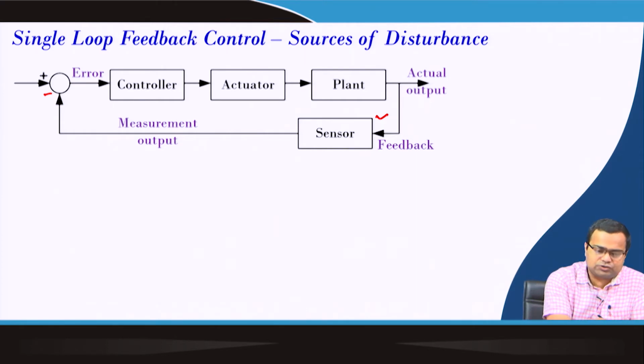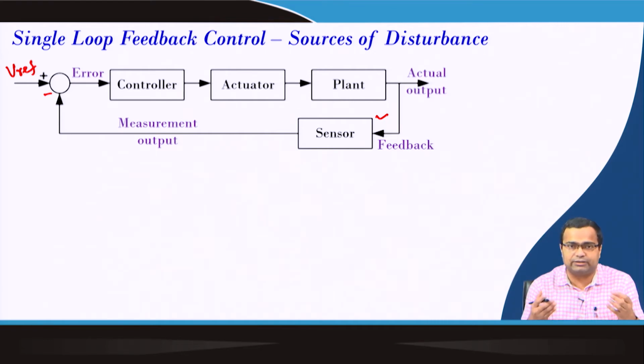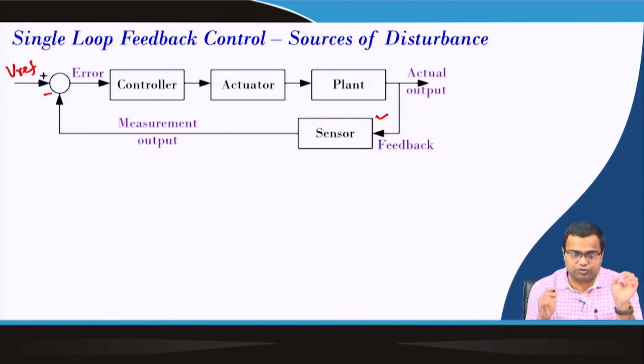Then this goes to a comparison with a reference signal. This reference can be a voltage if it is a voltage regulator. If it is a current regulator, this can be a current reference, and we need to sense the current which we want to control. In some cases we want to control the inductor current, in some cases we want to control the load current.